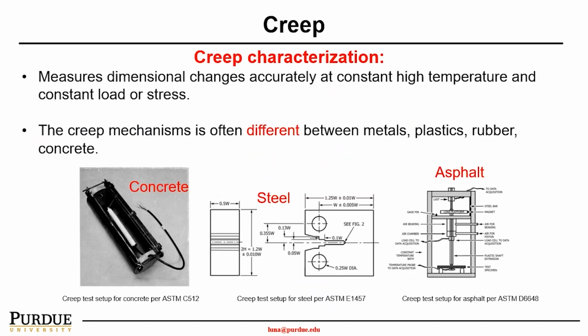How to characterize creep, right? Creep characterization is done by measuring the dimensional change accurately at constantly high temperature or constant loading or stress condition, right?